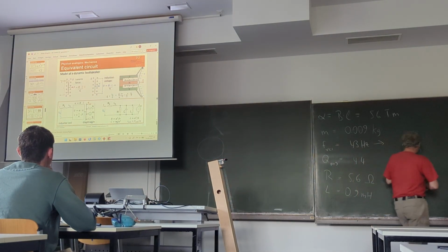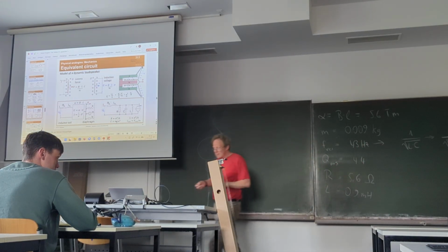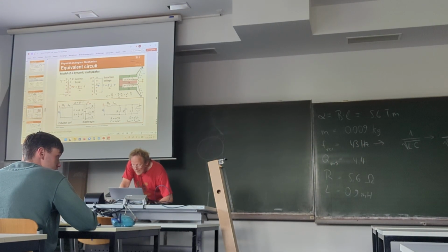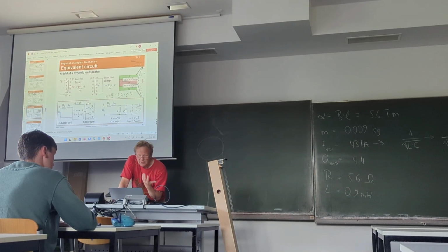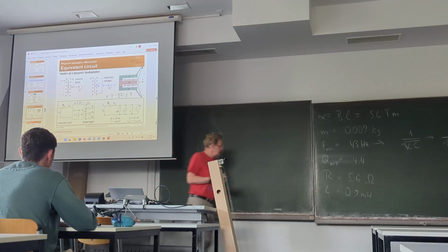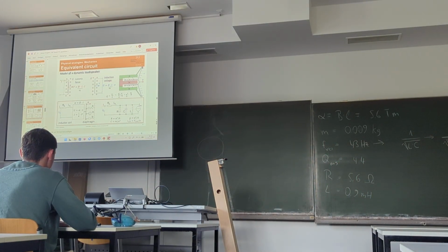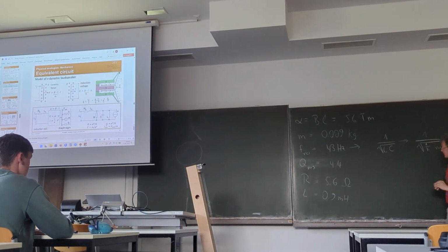So in this mechanical formula, at this point here, is the mass. Then the inductivity L is proportional to 1 over K. So a very stiff spring with a very high K corresponds to a small inductivity. And so we replace this here with 1 over K. Okay, so that's the formula for this resonant frequency.